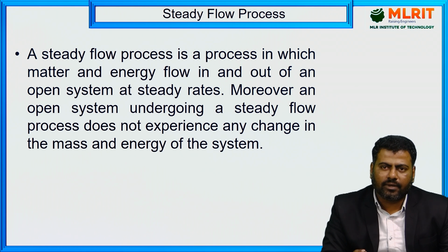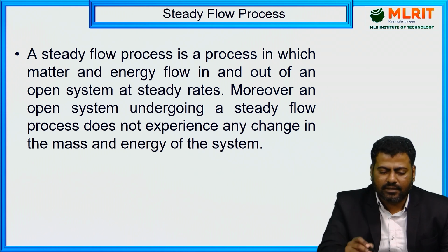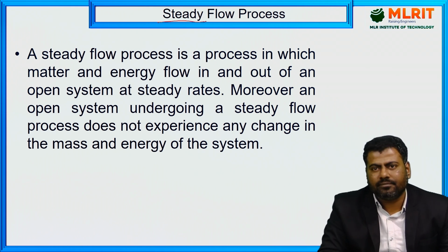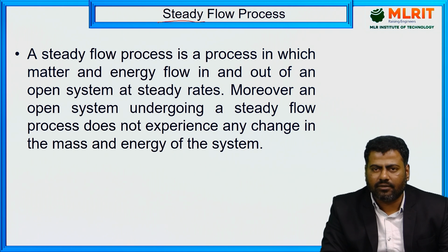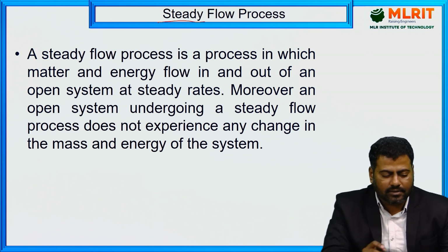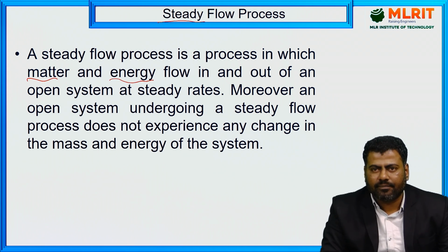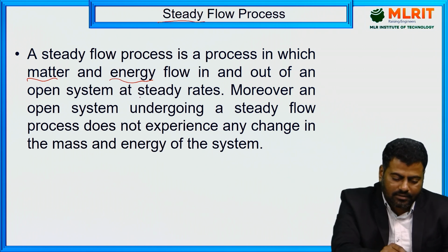We can apply this to unsteady flow processes also. But the steady flow process is for simplification purposes. For analysis, we can easily consider the steady case, and then implement it for unsteady flow processes. Right? See here, a steady flow process is a process in which matter and energy flow. The matter is nothing but the mass, and we have various forms of energy. So energy transfer flows in and out of an open system at steady rates.